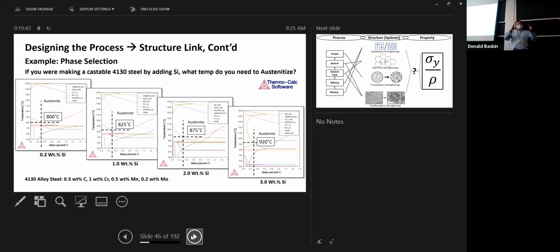That's important. You've got some complicated mold geometry. You want to fill this thing without any porosity. If your material is thick and gooey, it's not going to fill the mold very well, right? So one way that metallurgists and foundry people have found to solve this problem is to add silicon. Silicon increases the fluidity of, like I said, steel and aluminum. I don't know if it does it to nickel, but I know it does it to steel and aluminum.